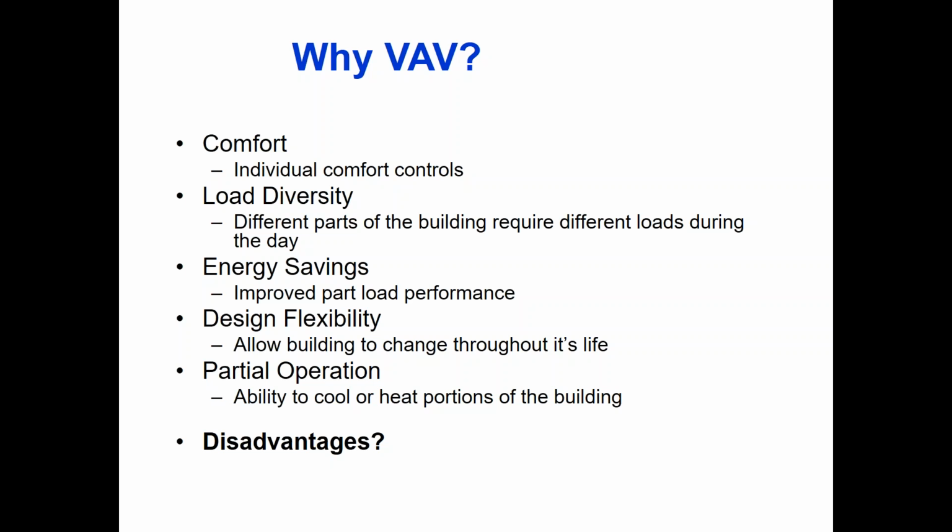Another benefit of a VAV system is load diversity. So what does that mean? You probably all have been on enough webinars of mine or classes to know that I always complain about things being oversized, because everything is oversized, like literally everything in our industry is oversized. But oversizing equipment is really detrimental on a VAV system. In fact, we're going to, I don't want to say undersize because that sounds bad. We're going to size the equipment smaller than we would if we didn't have VAV.